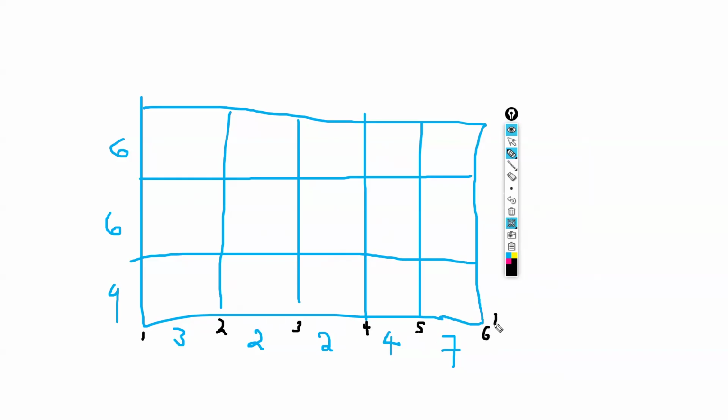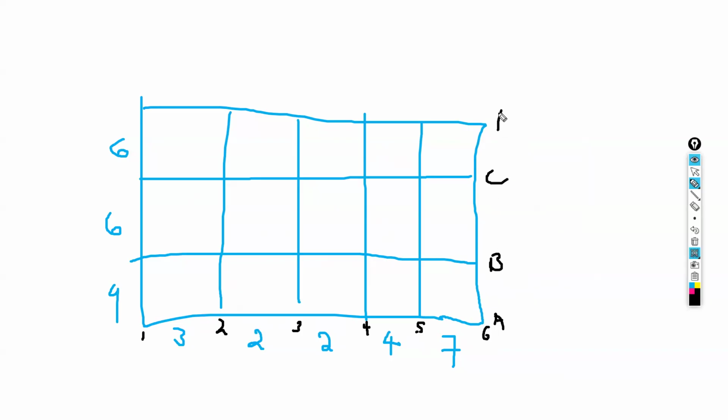This can be represented as A, B, C, and D. Now, when you have not created an AutoCAD file, I'm assuming this is your grid. These are your grid spaces which you have achieved. You may use the orthogonal axis generator to create this construction grid at once.